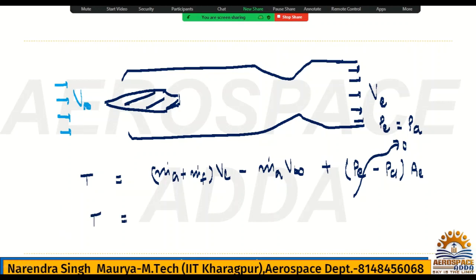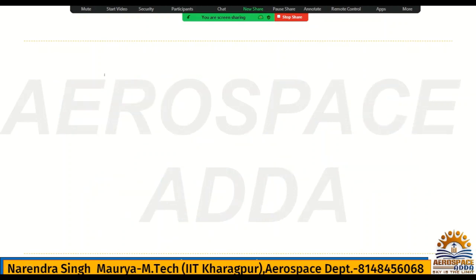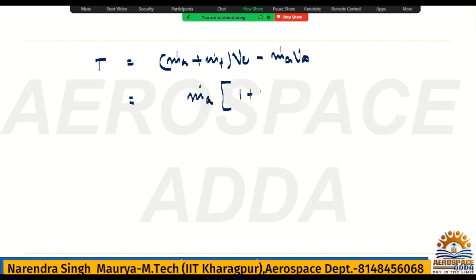Now what do we have? So T is equal to (m dot A plus m dot f) VE minus m dot a V infinity. We can write thrust is equal to m dot a in bracket (1 plus m dot f by m dot a) VE minus V infinity.